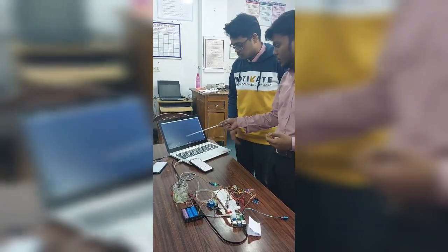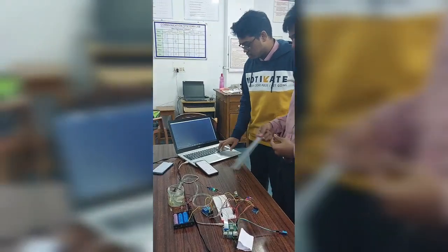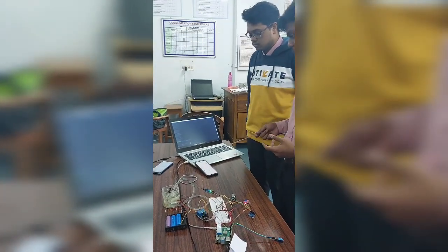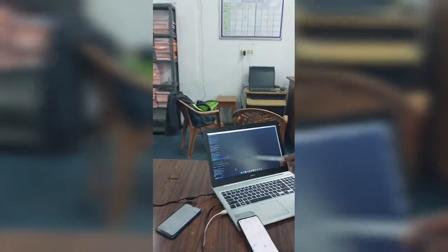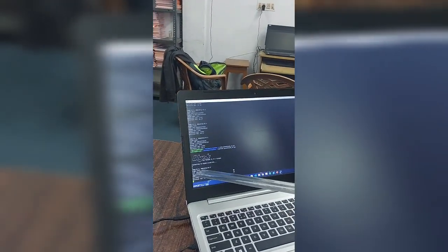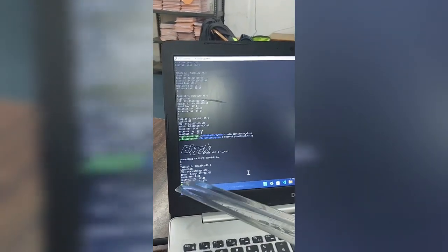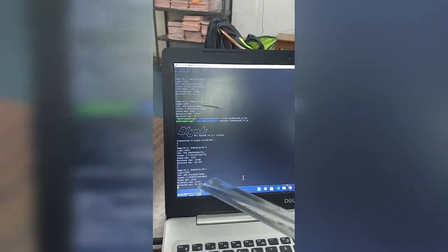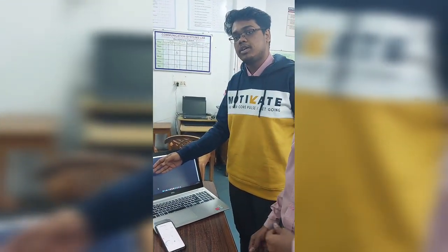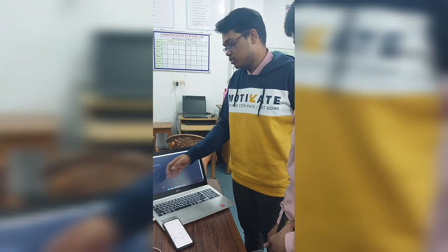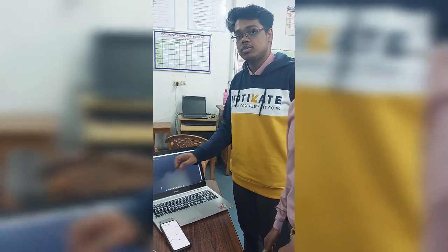And currently we are going to run the code which will help us monitor and measure the agricultural parameters. Here it is connecting to the Blynk Cloud service provider, and in the serial monitor we are getting various values such as temperature, light, CO2, sound raw, moisture and moisture value, etc. We are transmitting the data at an interval of 2 seconds, because Blynk says that if we transmit data in bulk, it may disconnect our services. So we are sending the data at an interval of 2 seconds.